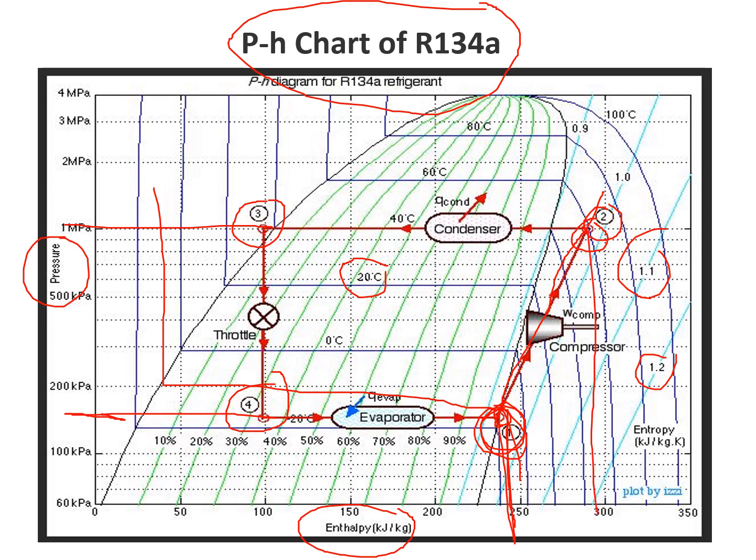Now from 2, the condensation takes place, and that 2 to 3 process is in the condenser. So you have to follow the same pressure line till it reaches the saturated liquid, if it is a theoretical one. Okay, so this is the 3.